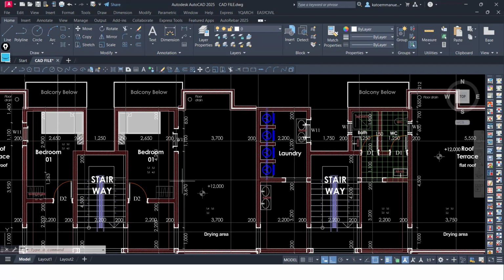Areas like washrooms, balconies, terraces, we use solid slabs because ribbed slabs are not that good in sustaining conditions of water. In case there is seepage, it will create some weak points in the slab. You get it? Also, you need to look at the functionality of the building.